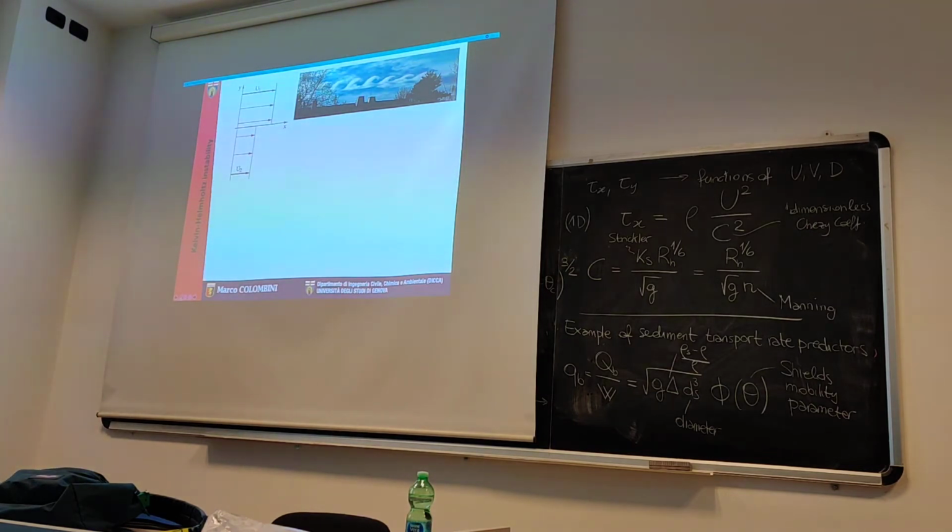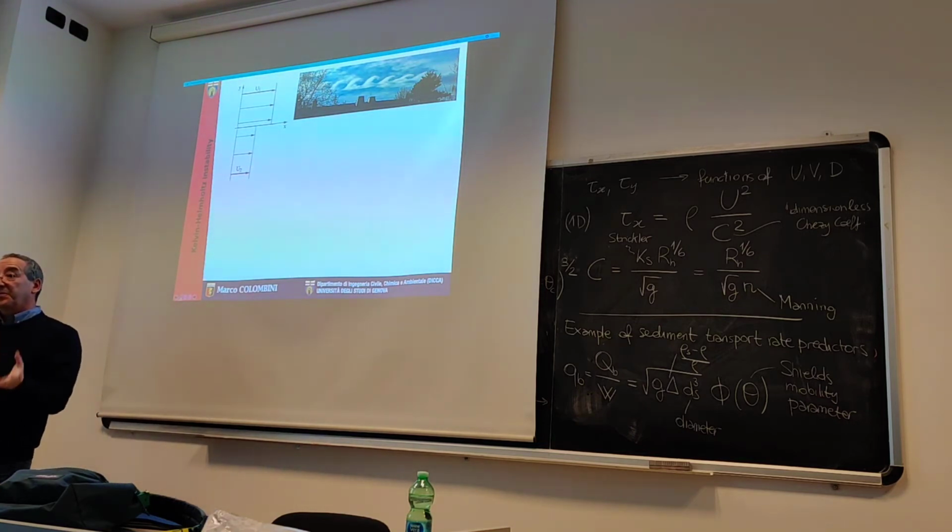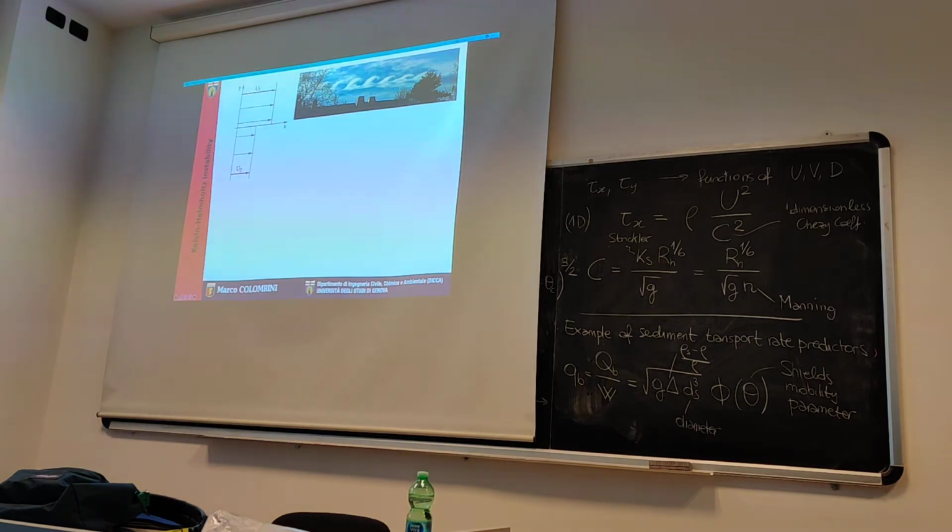You can see an example of Kelvin-Helmholtz instability in the clouds in the photo there. And it's a kind of instability that starts when you have a shear. So we have two layers, like sketched in the sketch on the left. You have two layers with different velocity. At the interface of the two, you have a shear, and this shear can be unstable, leading to those kinds of patterns. Okay, instability and pattern are two things that are strongly connected, one to the other.